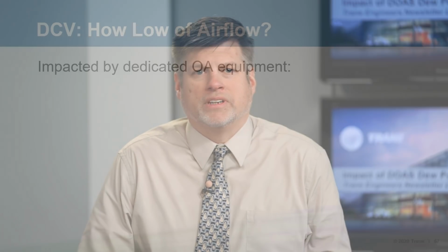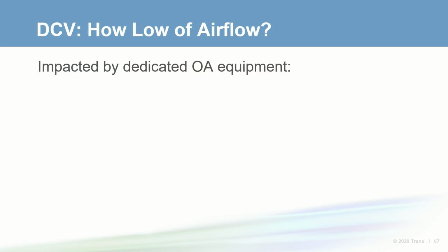Whether unit level or zone level DCV is used, the dedicated outdoor air unit should measure airflow delivered and not let the unit airflow drop below the minimum allowed. The unit's minimum allowed airflow will vary based on equipment manufacturer, equipment type, and options installed. DX refrigeration is often the primary concern. A unit with limited stages of capacity control may have limited airflow turn down if allowed at all. However, many DX dedicated outdoor air units can be equipped with variable speed compressors and electronic control valves. With proper unit controls, this can allow DCV to turn down fan airflow to 30% of design.